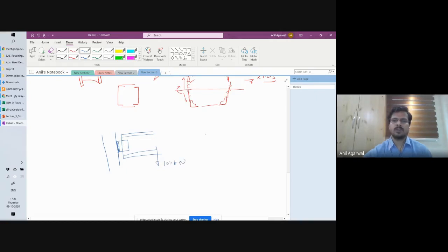And what I find is that one bolt has a capacity of 25 kilonewton, or let's say 40 kilonewton. So what I cannot do is use 2 bolts, get 80, and then also add a weld that will give me another 20. That is not acceptable.